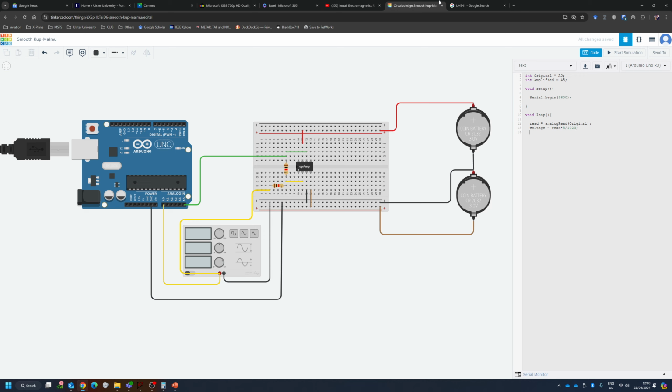Nice. Now I just need to Serial.println my voltage and close loop. So I'm doing the analogRead of the signal that I want, and then I display the signal that I want here. I convert that signal into a real voltage so we can see it. I will open here the serial monitor, and the scope is active, and let's start the simulation.